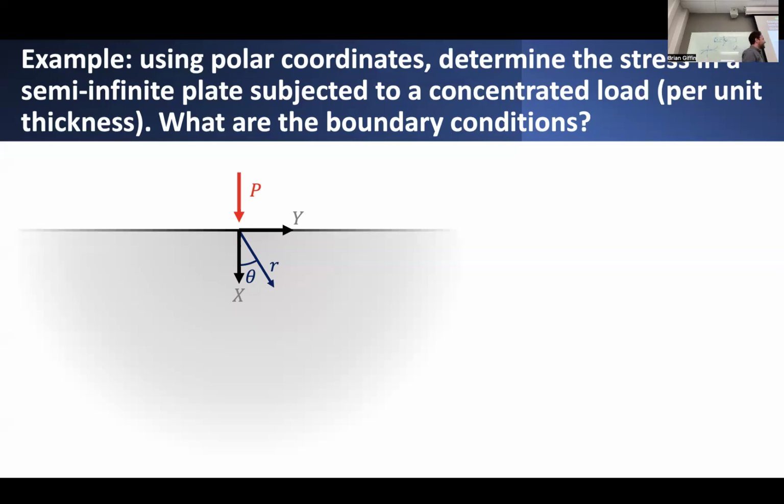Now, you might say, that's wrong, right? That can't happen in reality. Well, we're working with a mathematical idealization, and this is really where the limits of elasticity come to their end. It's important to acknowledge that even though we can construct and pose these types of problems, are they really physically meaningful? Can we even reproduce these scenarios in real life where we have a truly concentrated load at a single mathematical point? We can certainly set up and solve the problems, and we'll do that, but I want you to think about the validity of this kind of answer.